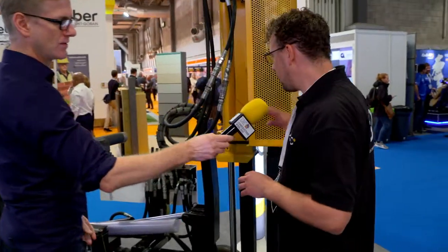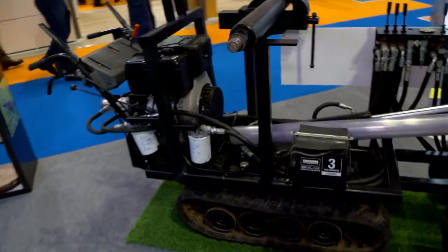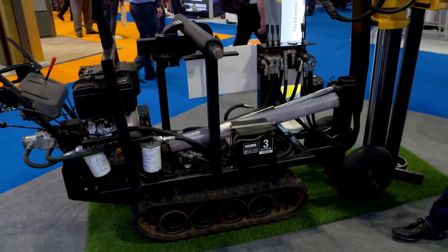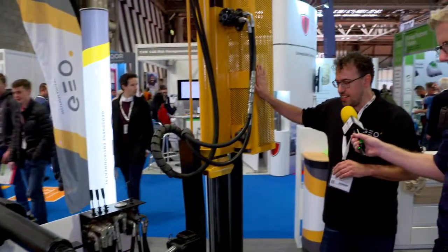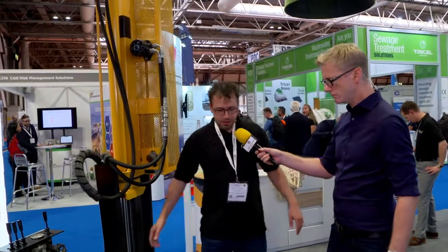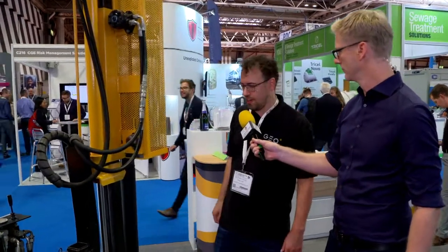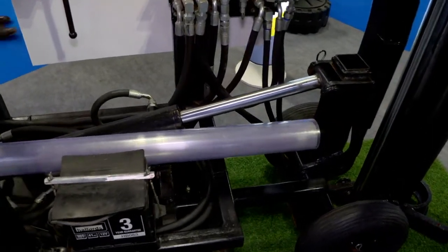This is one of the smaller rigs that we have in-house that we do a lot of the geo-environmental work on, but also some of the foundation design work. Capable of boring down 5 meters, 10 in the optimum conditions. It's nice, it gives you good soil profiles, it's low-tech, a percussive hammerhead knocking these tubes into the ground, and then we're pulling out soil samples from these tubes here.